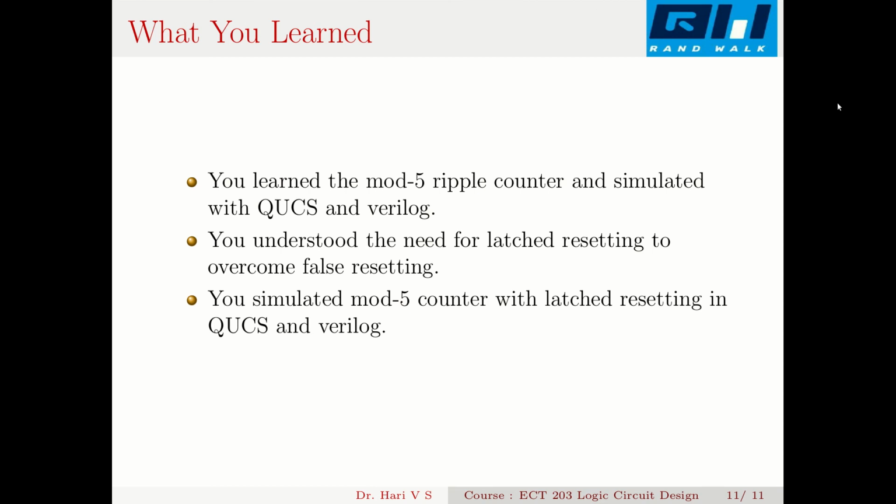So now what you learned in this video is that you learned the Mod-5 ripple counter and simulated it with QUCS and Verilog. Then you understood the need for latch resetting to overcome false resetting. Then you simulated a Mod-5 counter with the latch resetting with QUCS and Verilog.